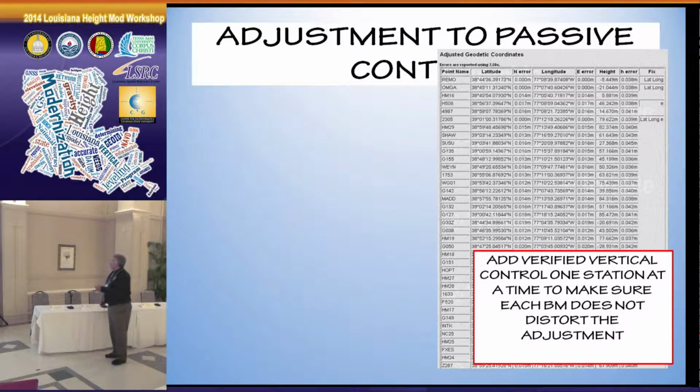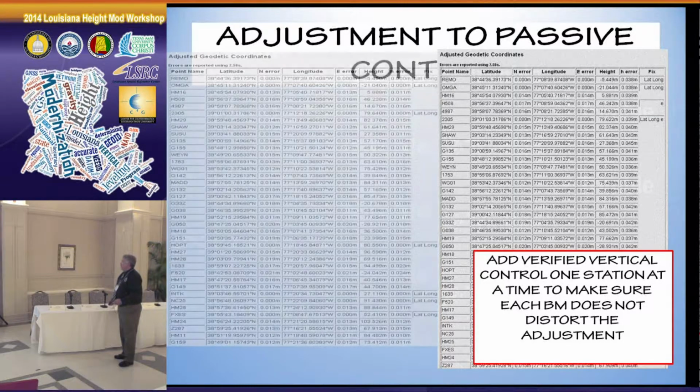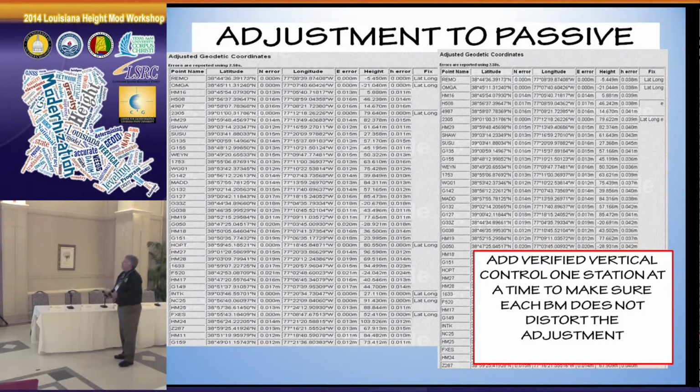So all these ellipsoid heights have been changed. They're 4 centimeters, 3 centimeters, 4 centimeters, because we've constrained the NAVD88 values. They don't all agree, do they, when you plug them in that little formula? And that's the way it is. There's the comparison between the ellipsoid before and after the orthometric adjustment. It's 1.5 to 4. That's how it changed.